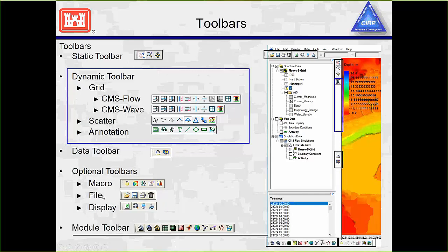File, there's opening, saving, standard things, display, refresh, and frame to the extent. There's display options, and then a plan view. So if you had gotten into some kind of rotated angle, you could click this key to get back to a flat, looking down type of view.